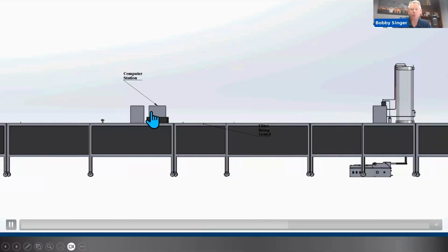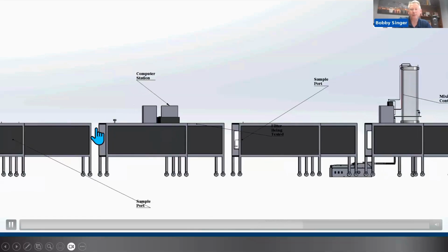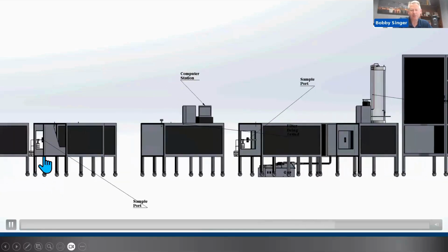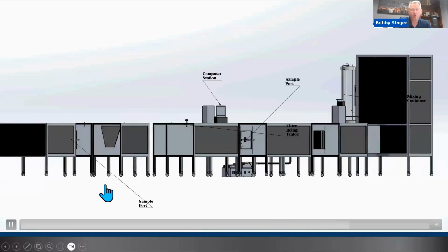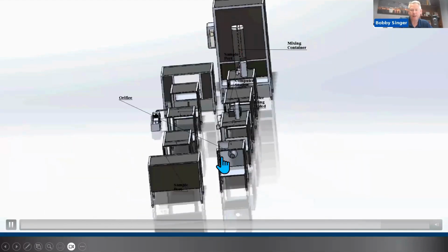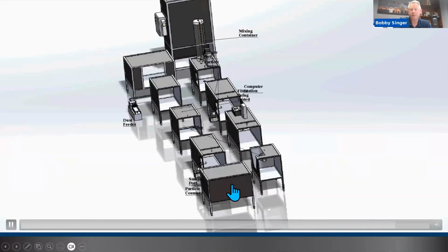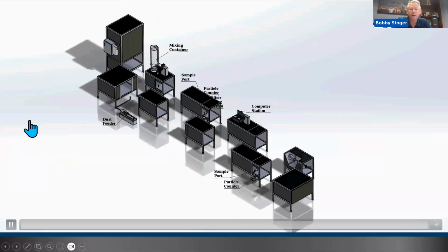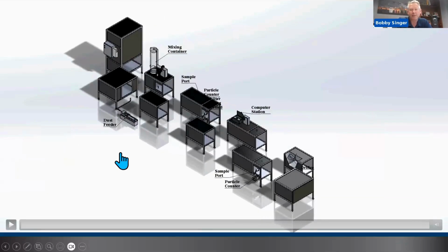That's just how we would control airflow, the particle counters, things of that nature. The downstream end, you'll get a backside view of the flow orifice in a second. And we'll get an up close look at that in a minute, but right there would be the flow orifice. And then the most downstream section has HEPA filters in it, so we're cleaning the air before we dump it back into the space.